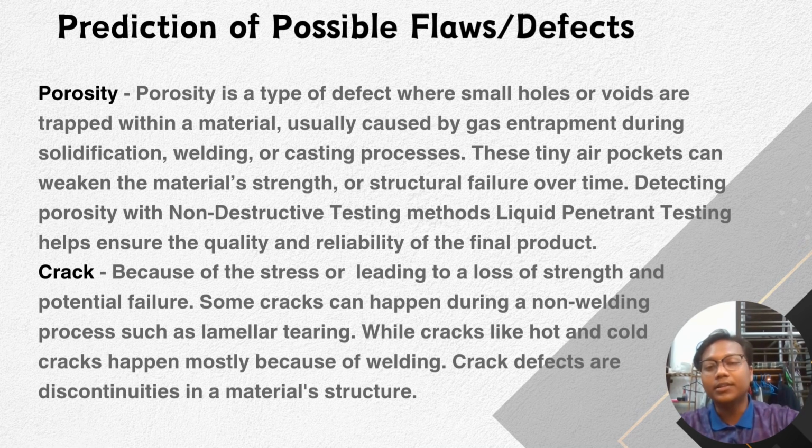The second one is cracks. Because of stress, leading to a loss of strength and potential failure, some cracks can happen during a non-welding process, such as lamellar tearing. While cracks like hot and cold cracks happen mostly because of welding, crack defects are discontinuities in a material structure.